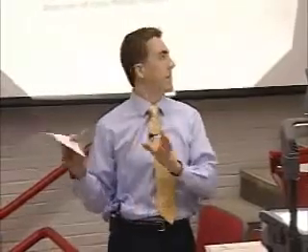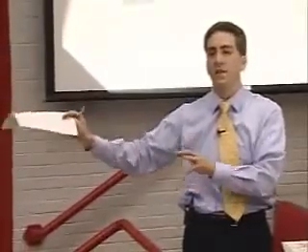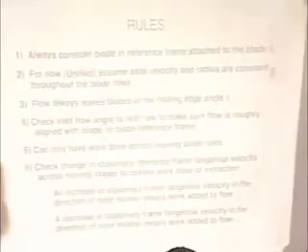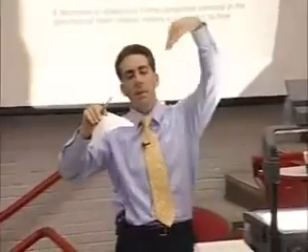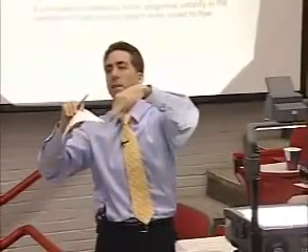We're going to assume that this is a well-designed machine. You do get a lot of fancy kinds of stalls in these engines, but it's not the first thing you're going to try and solve. Right? So you're going to assume that the flow always leaves at the trailing edge angle. One of the things that's useful, and I'll show you in a minute, is that you're going to check the inlet flow angle to make sure that the flow coming into the blade is roughly aligned with the blade leading edge. If it's coming in like this, it usually means you have something wrong in your velocity triangles.